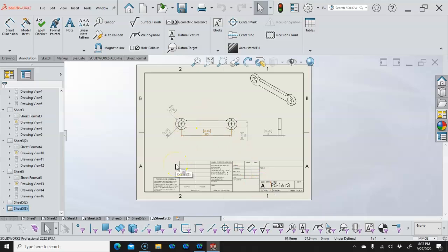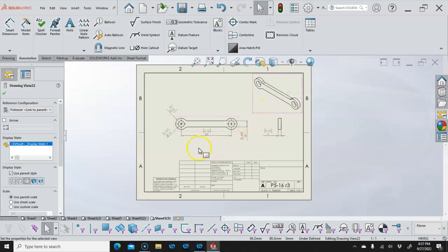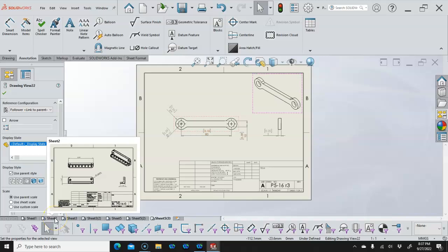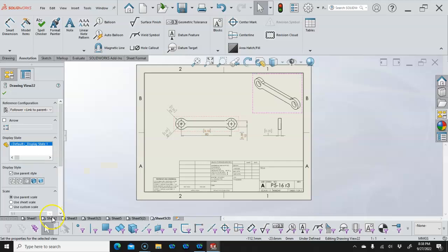All right, so very quickly with the configurations, this is kind of a special case. Usually, depending on the complexity of the assembly, sub-assembly, I'll go through and add all of these views, make sure it's what I want, and then come back and do a dimension run, then do a tolerance run, then do an inspection run. And after 3 or 4 or 5 iterations of this process, I get a working package that is pretty much doing what I want it to do. All right, communicating effectively the build of these parts.